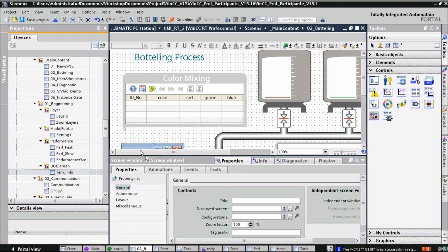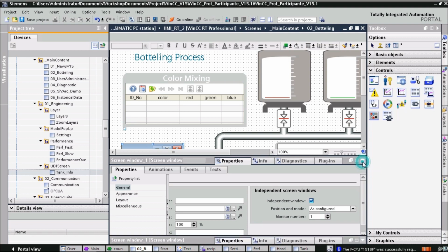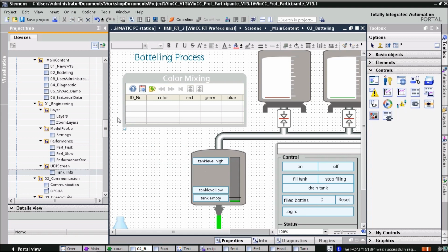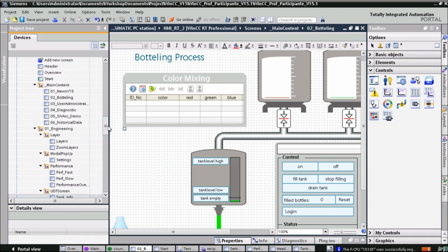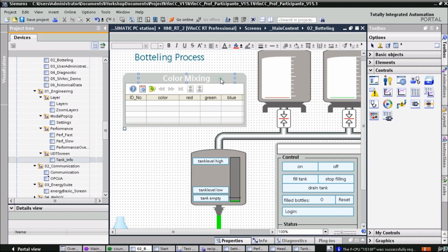So we start in the same way again, screen items, dot item, choose the same window info, and we access now the property of the screen window, which is tag graphics. And the IntelliSense again shows us all the properties of the screen window. One of them, what we want to access is tag graphics, and now we want to write the tag graphics into the screen window property.